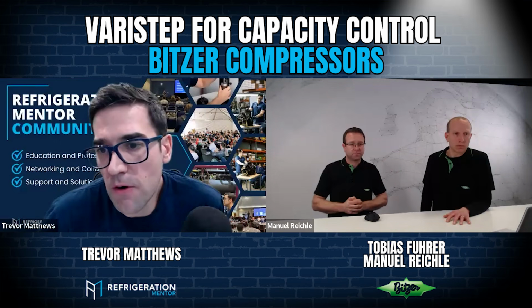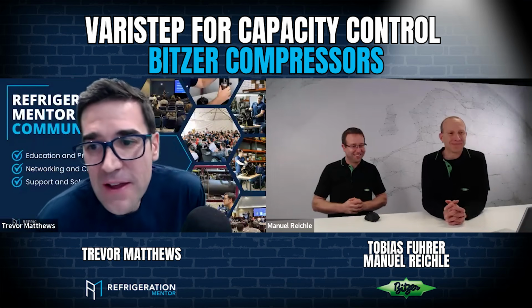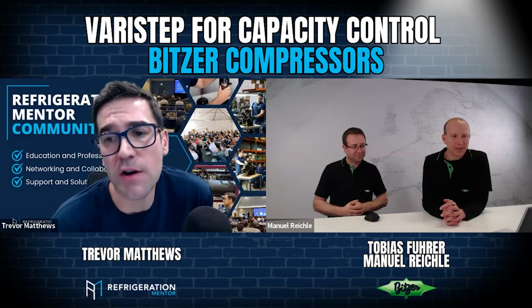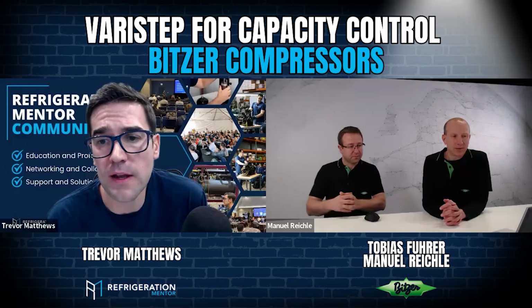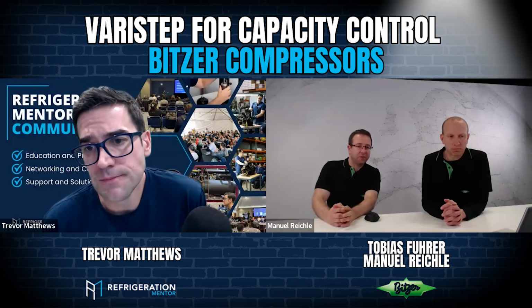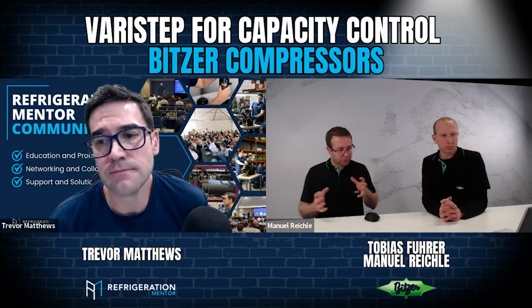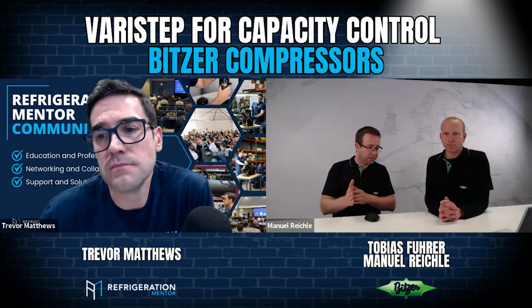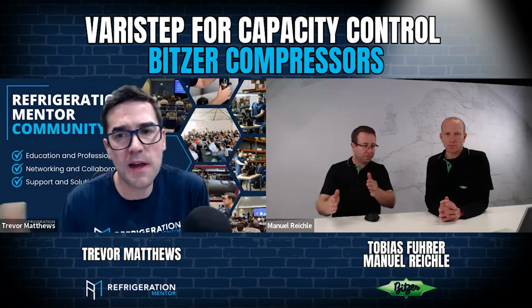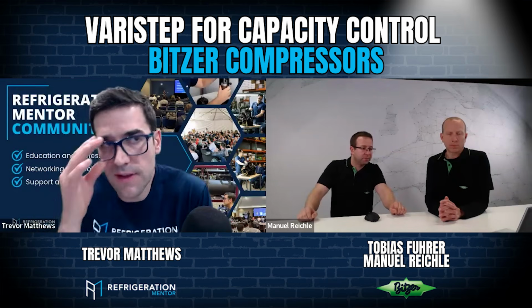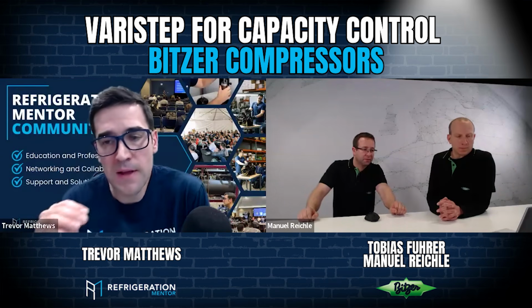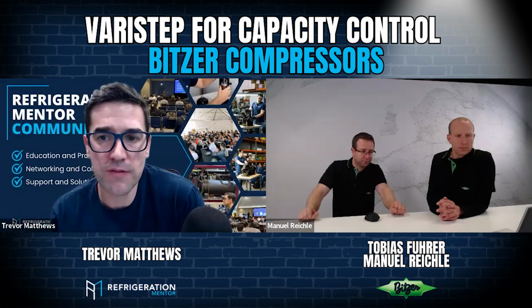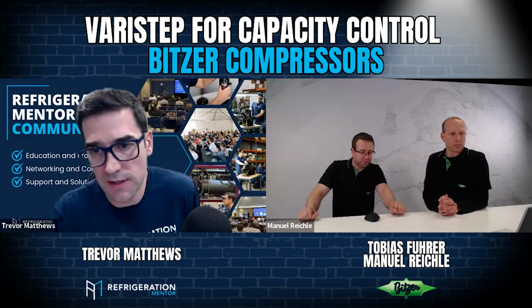Amazing. A couple more here. Thank you so much for your time. The question is, what is the cycle time for the pulse, or is there a cycle time on loading and unloading? It's not a fixed cycle time in the IQ module, but on average, the cycle time is around 30 seconds. 30 seconds, okay. Because it's dynamic. Because now it's not really coming from the Danfoss controller, the E3 controller, whatever. It's coming from the IQ module that's actually cycling it.